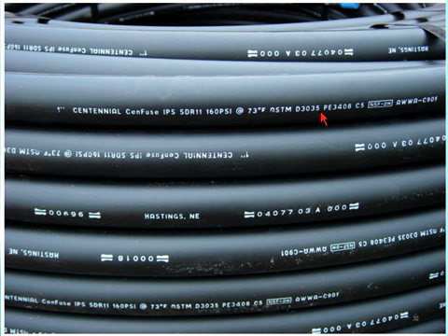There are 3 common things I'm looking for here. One of them is the pipe size. One of them is the DR rating, which we want it to be a DR 11 or better going down into the boreholes. And then we also want to make sure that it's the right PE cell classification number. That says 3408 there. Recently here, the industry standards are changing their number sequencing, and also I think now it's 4710. So you may see 3408 or 4710 in the field, and either one is fine.